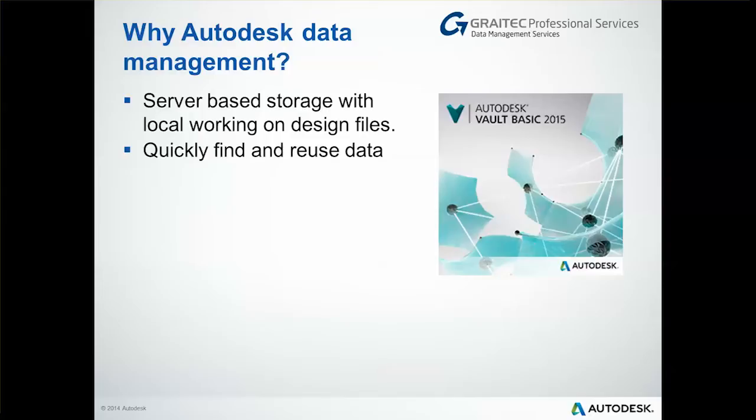Vault is a database, so it uses SQL. All your data is indexed, so all the properties and information contained within your files is extracted, which means you can quickly find and reuse data using these properties. Vault Basic gives you version history of your files, so you can track what's been happening since the initial creation of your document.